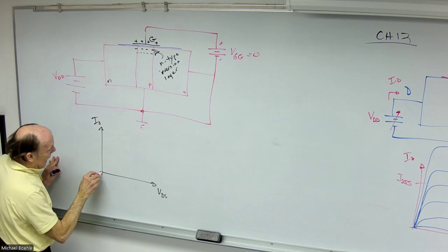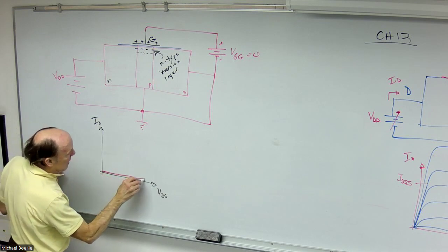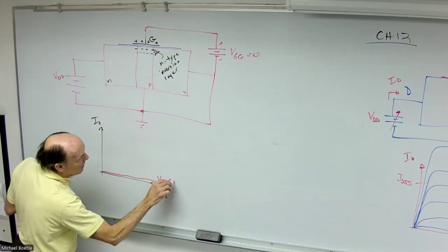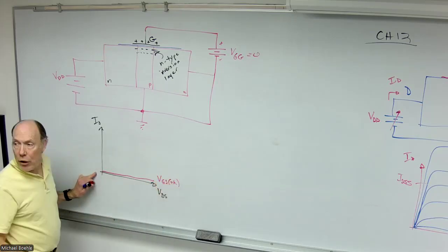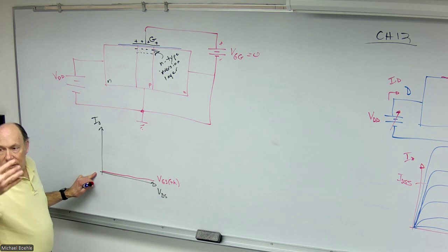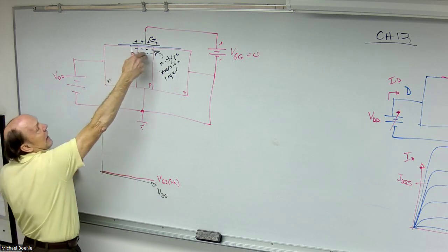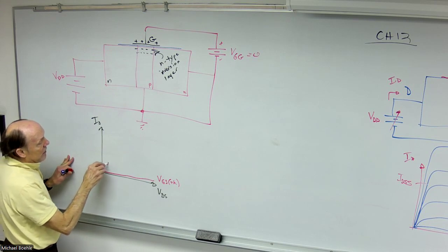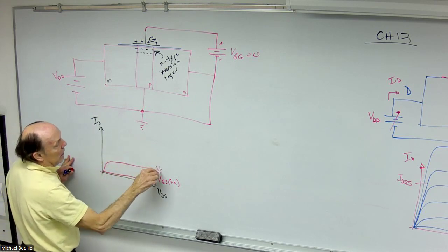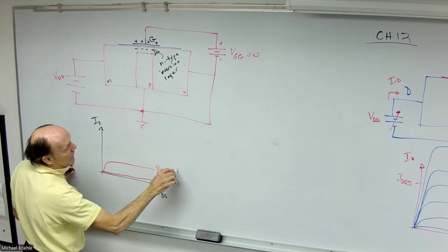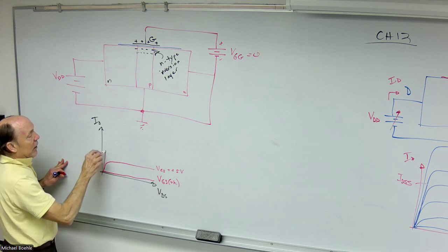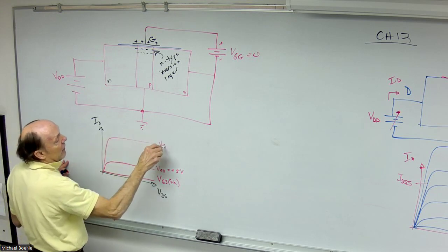But at some threshold gate source voltage, I just start to see current. If I increase the gate source voltage, make that inversion layer bigger, it is more conductive. Say 5 volts. Make it 10 volts, make it even bigger, even more conductive.